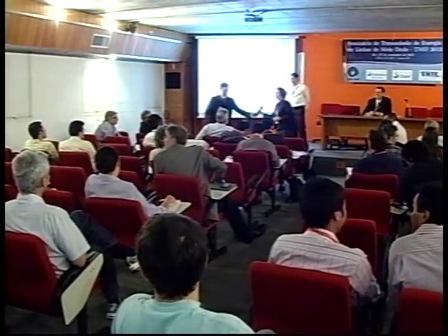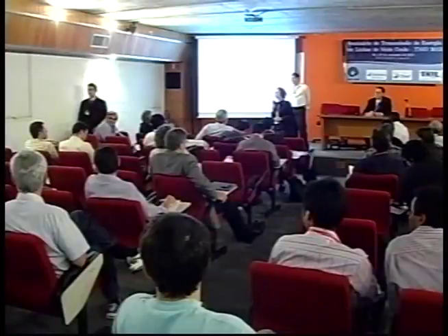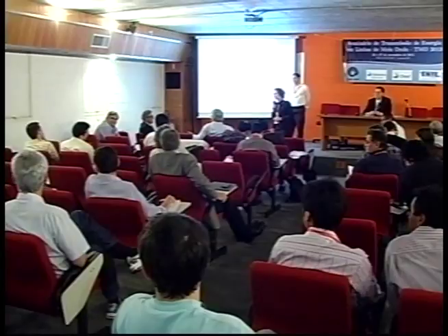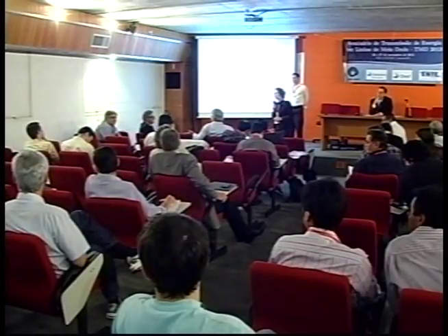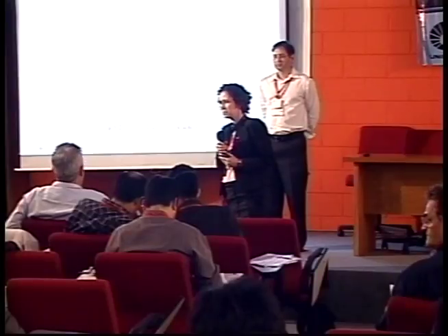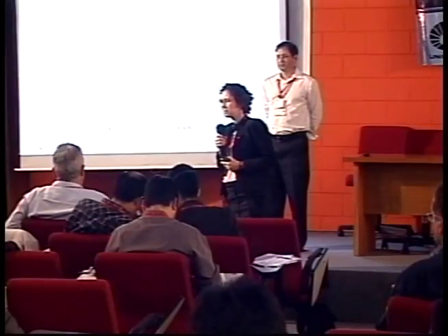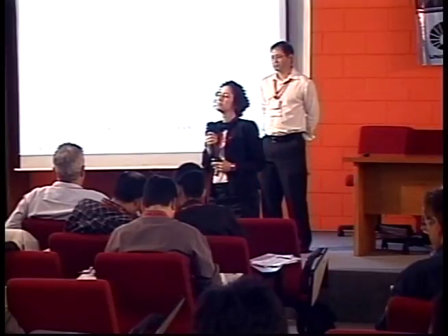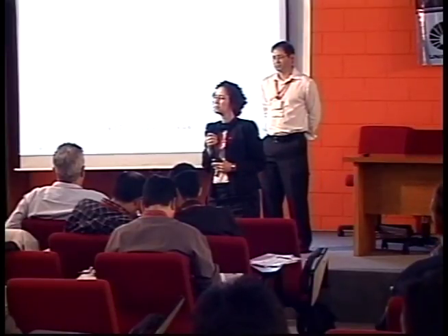But regarding the energy absorption, I'm sure you remember the conversation we had on CNPT regarding the inadequacy of the varistor models, for example, for ATP, to simulate or really show the capacity for energy absorption in surge arresters. When we put MOV92 in the circuit, it behaves as an ideal surge arrester. The current is always the same. You can support almost a million joules. But by the figures I have seen, the three-phase fault would eliminate a lot of surge arresters. They would actually fail.